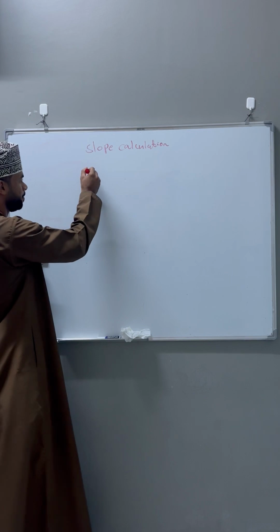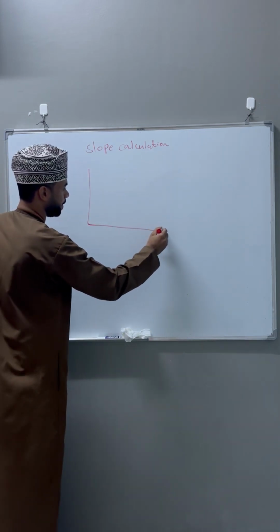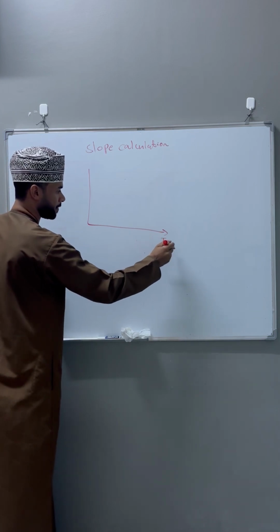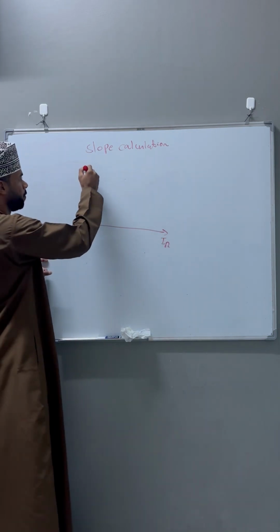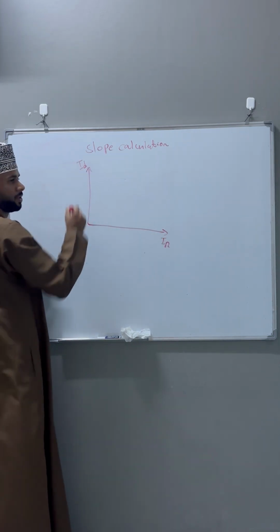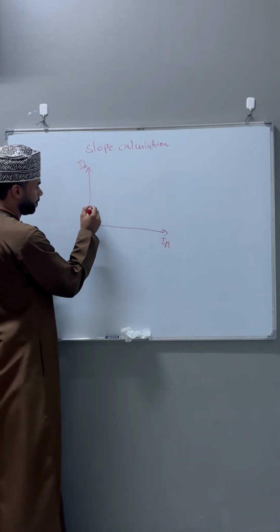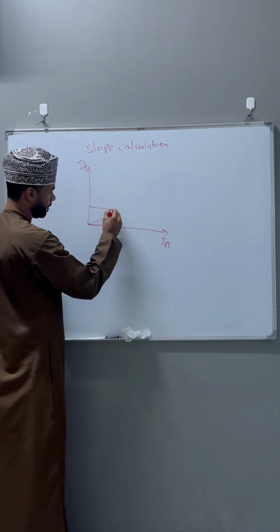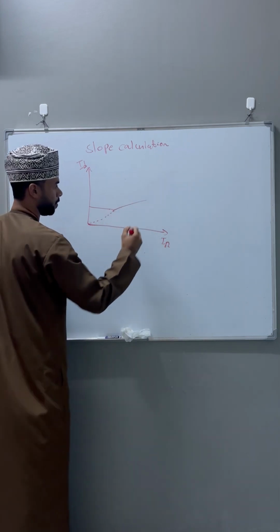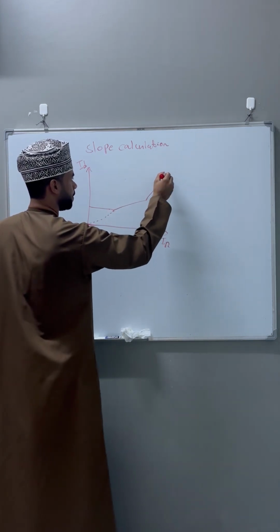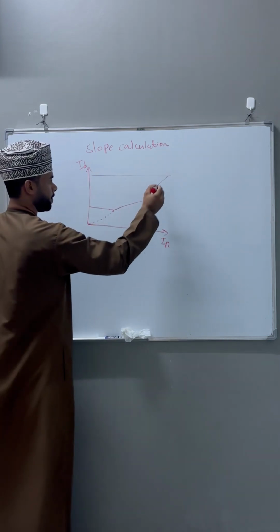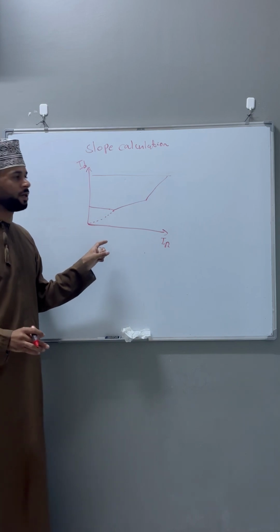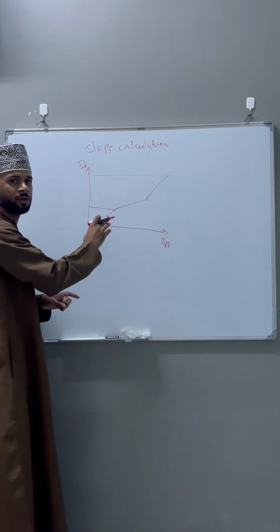Simply we'll draw the slope like this. Here in the x-axis we have something called I restraint. Okay? And in the y-axis we have I differential. Okay? So we'll draw the first line like this. Then we'll draw slope 1, then slope 2, then we have this line. Okay? So this way we will draw the slope, and all the points of the slope we need to calculate.